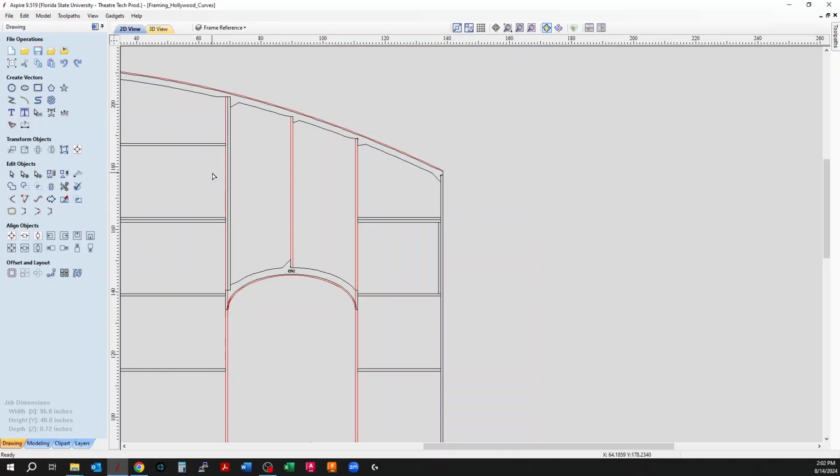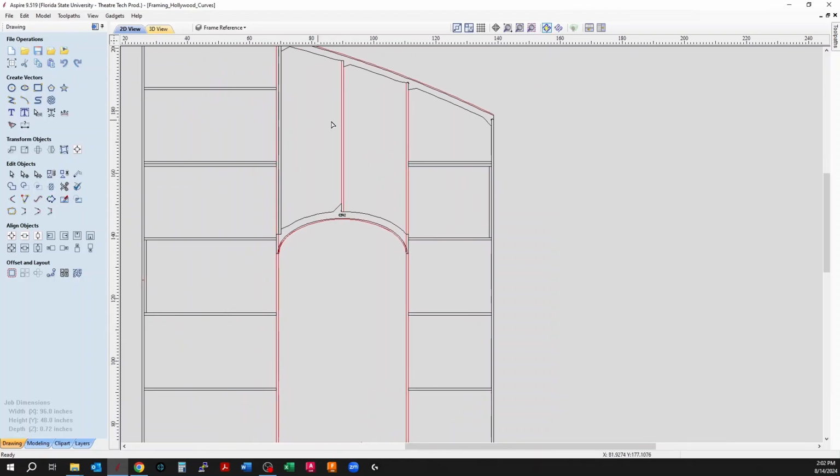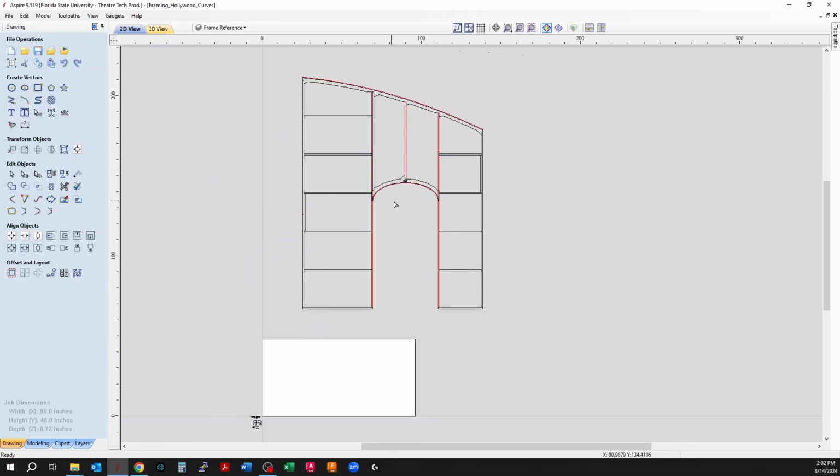So I can frame this side together, put it in place, frame this side into the CNC pieces, and the same on the other side. And then I've got seam support for all of my sheet goods there. So at this point it's looking pretty good. I'm going to start laying out to put my CNC parts onto the sheet, and I'm going to go back at this point, make sure that I've got all of my dog bones into areas, add the extra framing for my seam breaks for the doubles on the sides, and then I'll start laying out for sheet goods and putting my CNC parts into a sheet good layout.